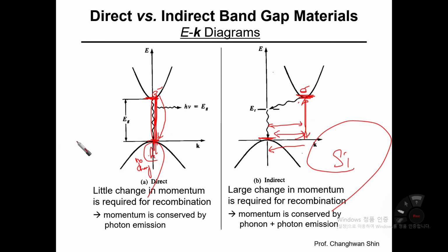But in this case, gallium arsenide, a III-V compound semiconductor material, and any conventional material used in optoelectronics, any semiconducting material that can create light, is not 100%, but almost 100% probability a direct material, because little change happens in momentum when the electron is losing its energy from the conduction band down to the valence band.